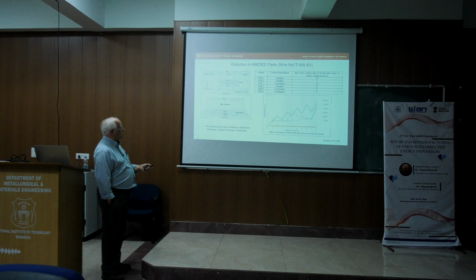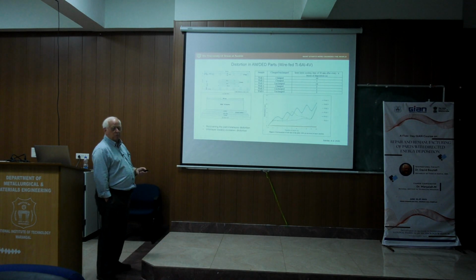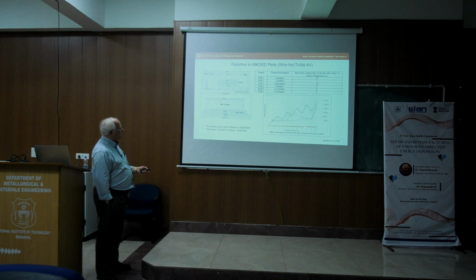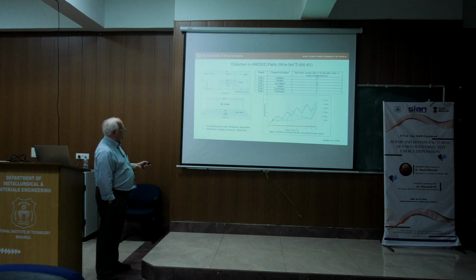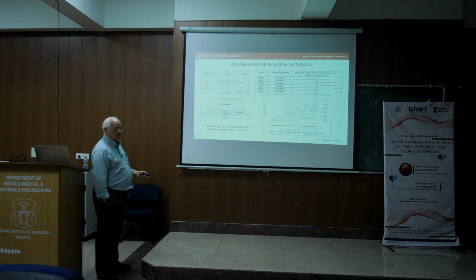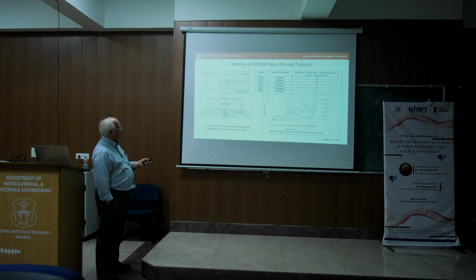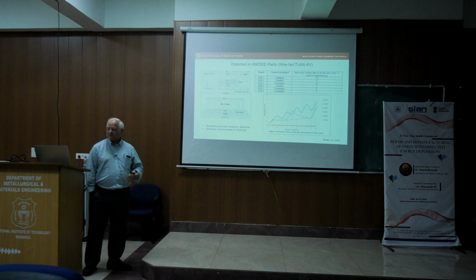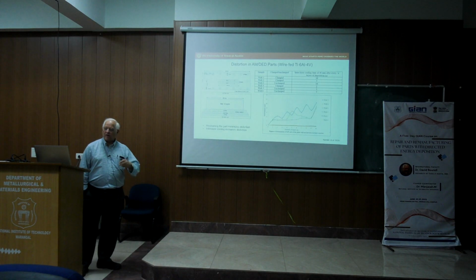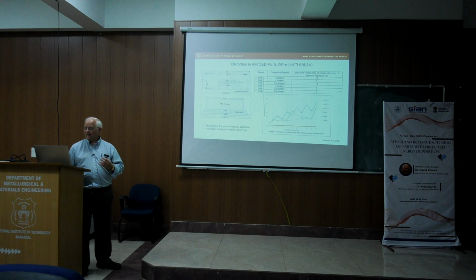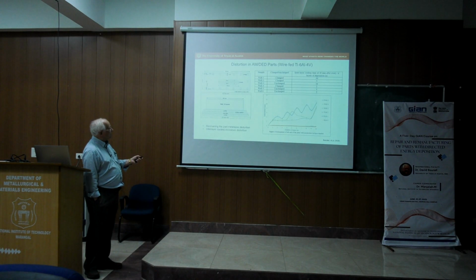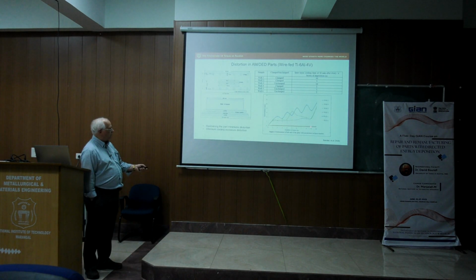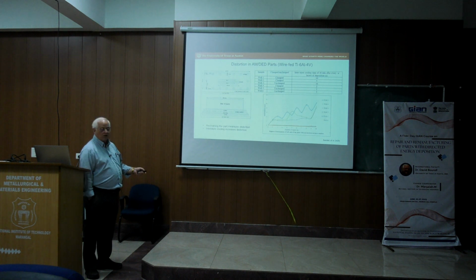So here's the bottom line. Now I think we can try to interpret this plot. Effectively, there are three scenarios where there's basically no distortion. These three are wall 1, wall 2, and wall 4, which were all clamped. So clamping the substrate to prevent it from distorting and moving actually has a positive effect on the distortion of the DED part. Basically, it kills the distortion altogether.